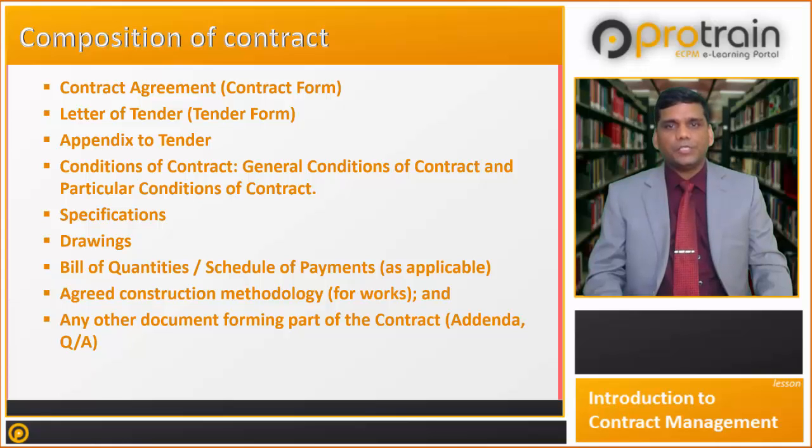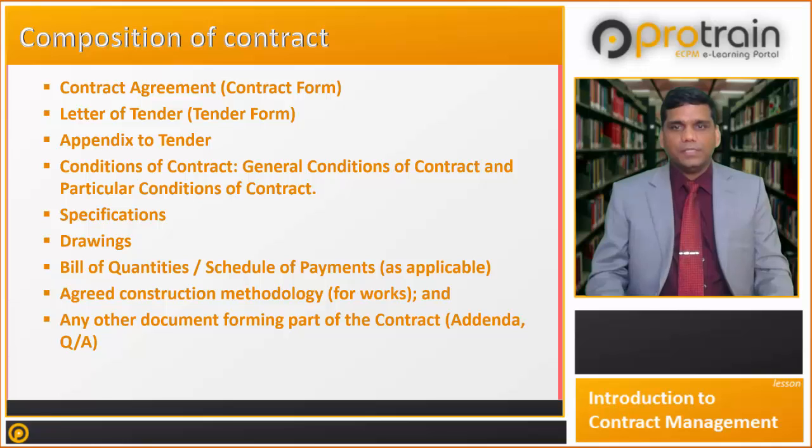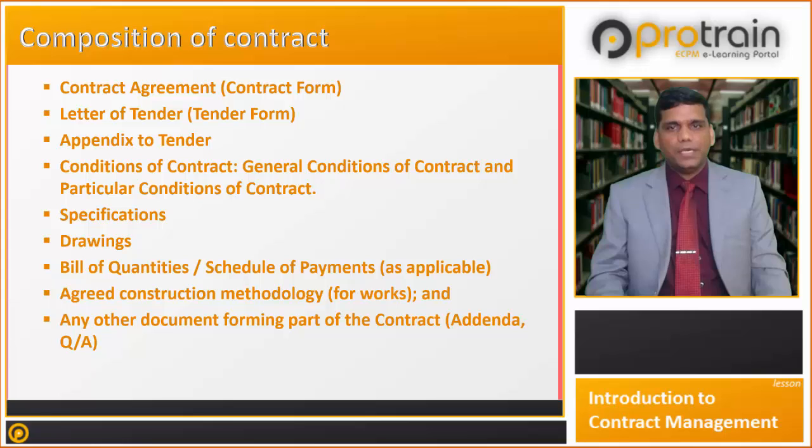Particular conditions should be in line with the local law and law of the contract. Clauses in particular conditions should not conflict with the clauses of the general conditions. Any revision, additions, omissions done by the particular conditions should be based on rational reasoning. Priority of documents is very important and it should be readdressed for every project through particular conditions.